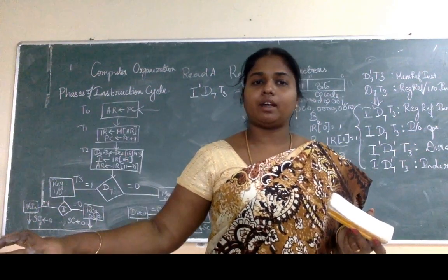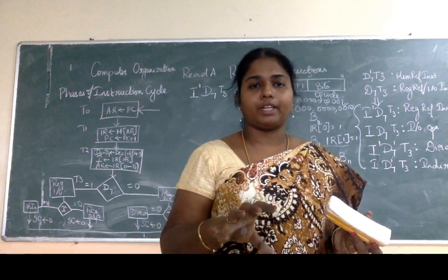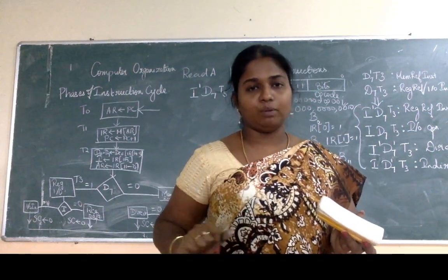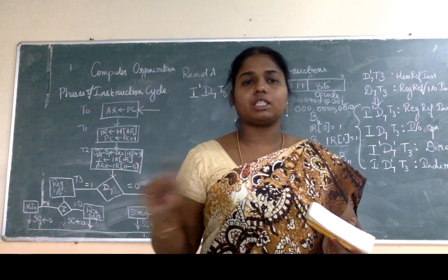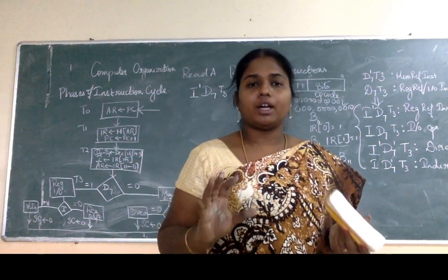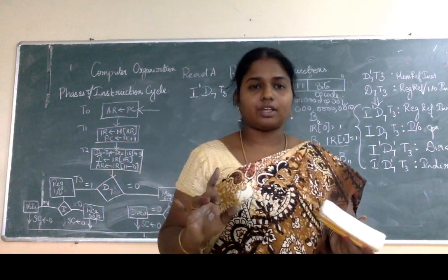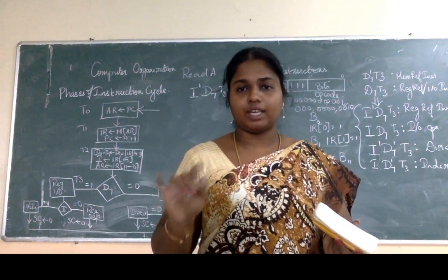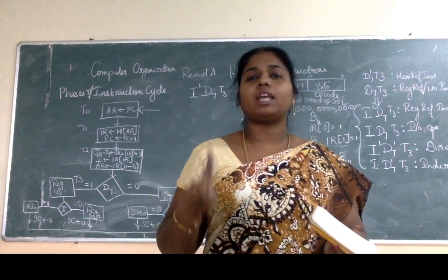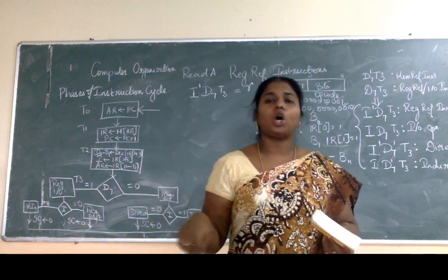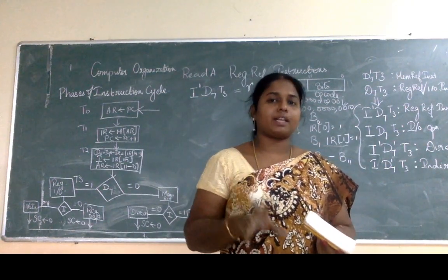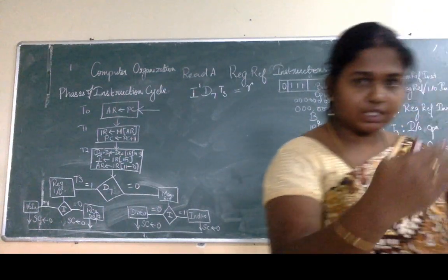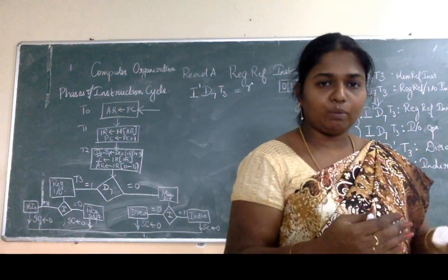It can either be the data register or the temporary register. There are two registers available for storing data other than the accumulator, the temporary register and the data register. For now, both are considered extra registers, and the instruction set denotes it as register E. So the first few instructions are going to be on either the accumulator or register E.